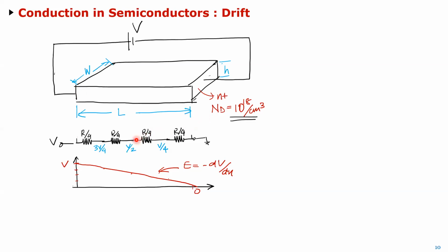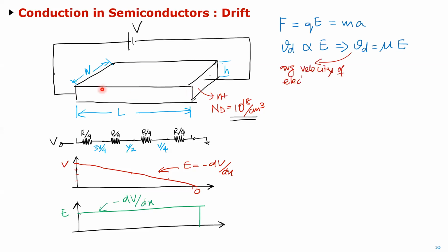And if you want to be rigorous, maybe, but it is charge neutral in the sense that even if the electrons are flowing, whatever is flowing in here is getting out here. Any cross-section volume I take is still charge neutral. So I can almost apply the same principle like before. If the potential is varying linearly, then the electric field is obviously constant throughout this phase. And if it is constant, then for any electron here, the force on the electron is Q times that electric field, because the electric field is uniform. So I can take it anywhere in that block.